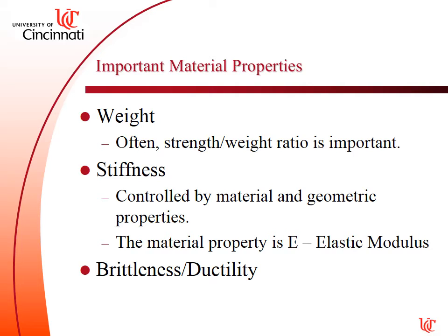But a lot of people would say concrete's a heavier material, and I just told you that steel is more than 3 times denser than reinforced concrete. How is that? Well, when concrete is made in a building frame, it typically takes on the shape of a square, a rectangle, a circle. It's a pretty bulky type of frame. The beams are rectangles, the columns are rectangles or circles, the slab is a rectangular slab. When you look at steel, typically we're looking at rolled steel members, steel tubes, steel I-beams, angles.